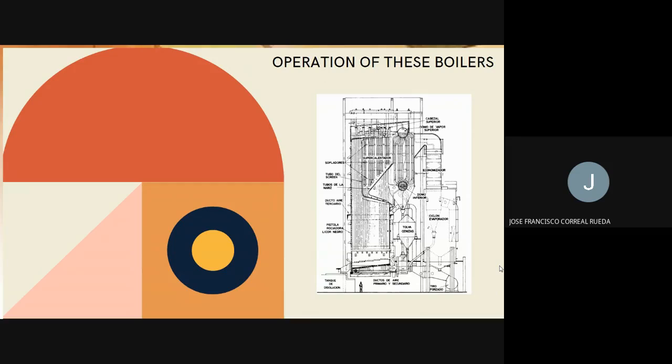The increase in feed water temperature represents an economy of the heat necessary to produce steam. To protect the tubes of the high temperature superheater from the combustion gas, a group of tubes called screen tubes and nose tubes have been arranged, where water circulates from the lower dome to the upper dome, generating some steam.